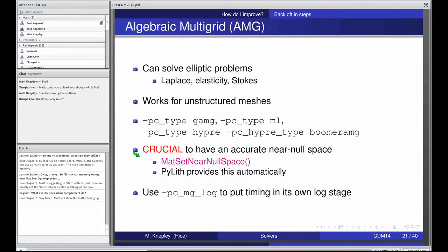And so in order to solve them efficiently, you have to respect the fact that the entire problem is coupled together. And this is what multigrid does. It solves the entire problem on coarse grids so that it's all coupled together, but it's inexact. And then it refines and solves successively more localized versions of that. So that's the idea behind multigrid. And it's pretty simple to write down for structured grids, but it becomes quite complicated when you have an unstructured grid.